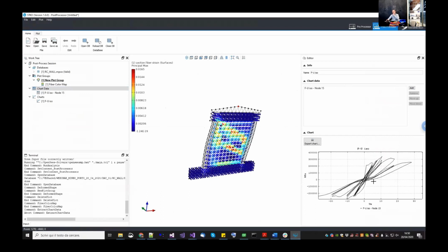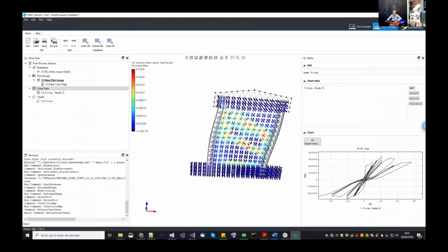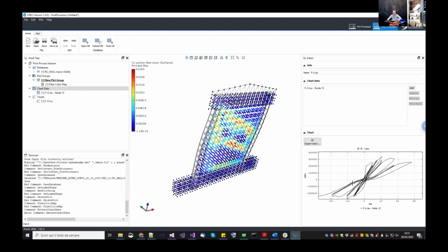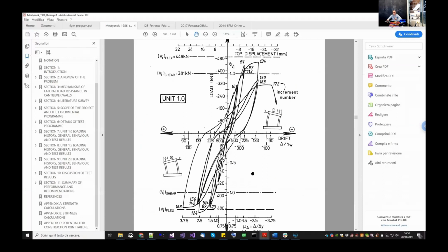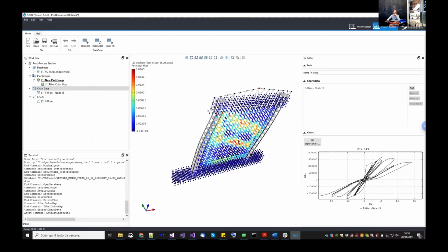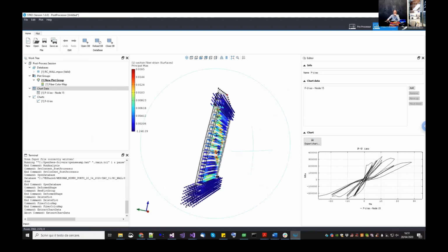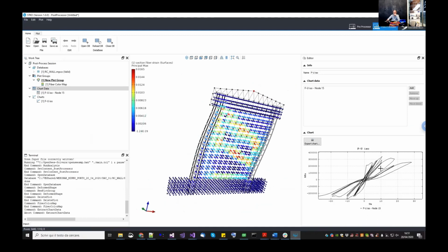So it's pretty fine, but if you want, you can add more features here to add more information, to play with it a little bit. I actually spent very little time trying to calibrate these models. You have to work with the fracture energy, because in this example there is no information on the fracture energy, and it is quite important. But this is now an example of how to use reinforced concrete, how to create a nonlinear shell with both concrete and reinforcement, and how to do a cyclic pushover analysis.